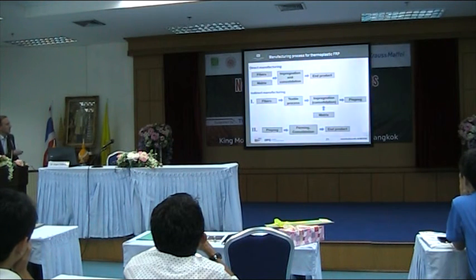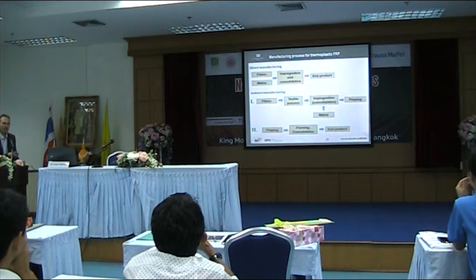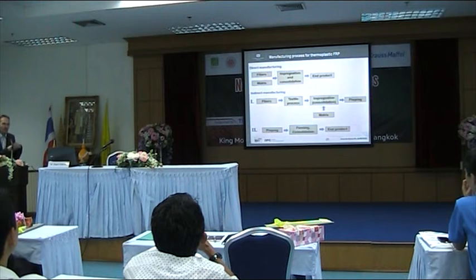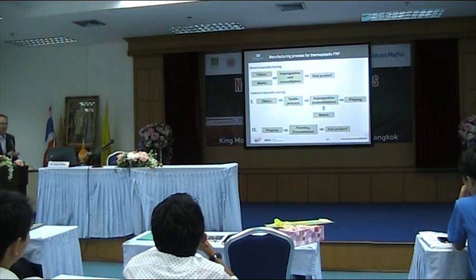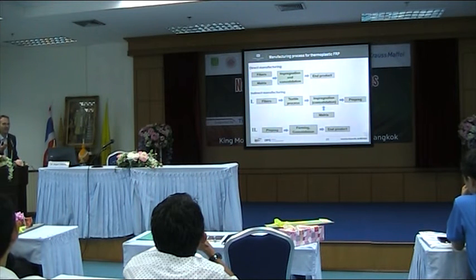So, two big differences. You have in direct manufacturing, you come with the fibers and the matrix, have an impregnation and consolidation in the end product. This is something typical extrusion technology or compounding technology. Yeah? The matrix and fiber go close together. In the plastification, you have an impregnation of the fibers, meaning surrounding each fiber with a matrix. Consolidation means cooling down and product. That's it. But if you want to have longer fibers, you need some textile pre-preg which you can use.